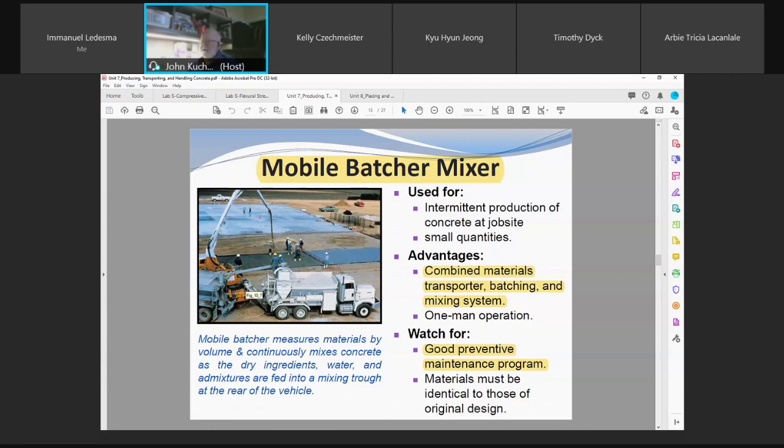So you're not weighing out aggregate by mass. It's strictly based on time and the speed of the auger. These are hard to calibrate. The beauty of these is, okay, you've estimated you need 10.5 cubic meters of concrete. How many times you've been on a job site where you're short? Now you got to wait for the last load.